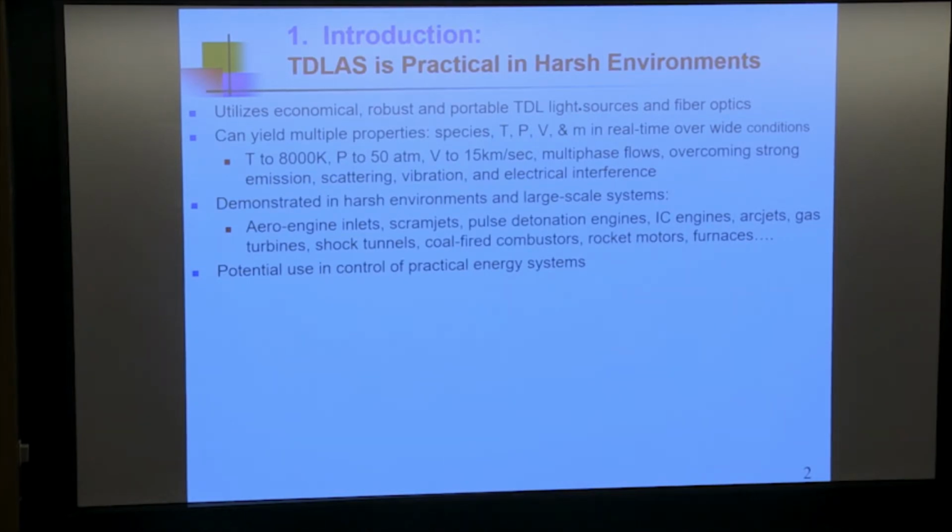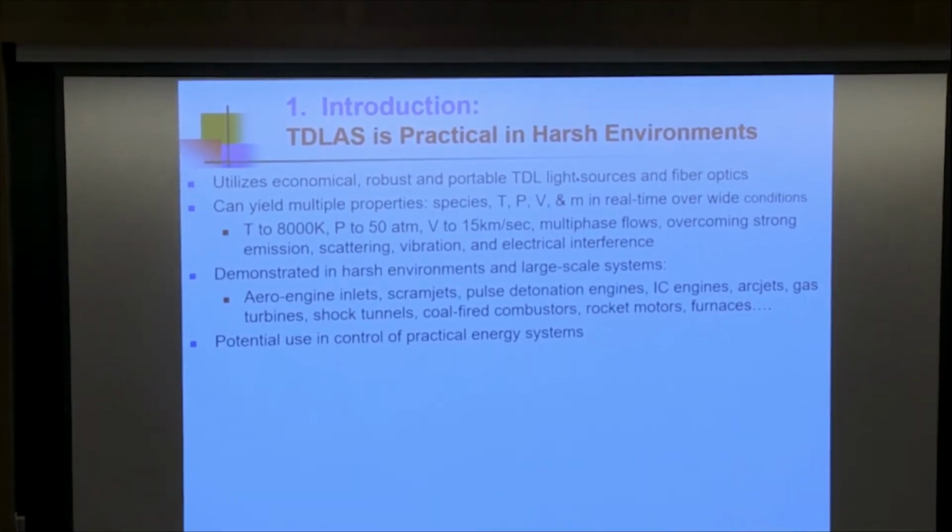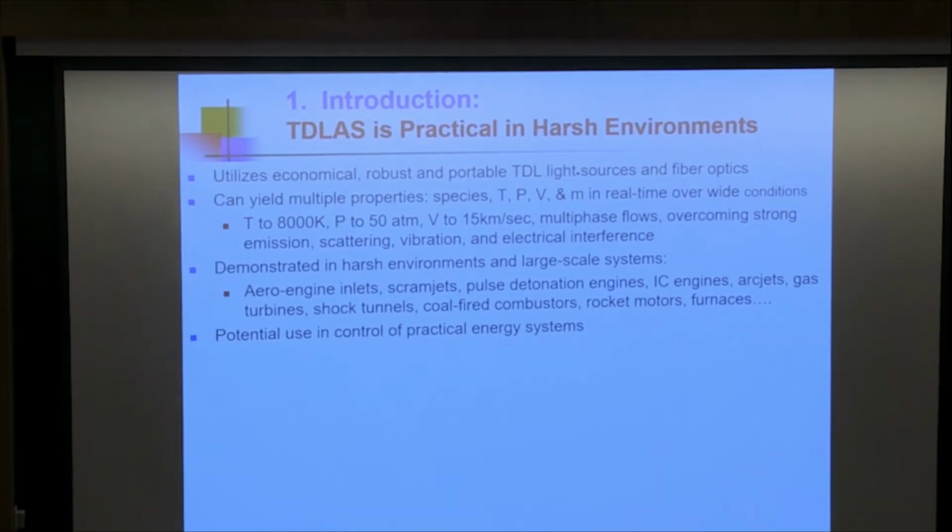And the main message is that this form of laser diagnostics is practical. You have to live with the line of sight aspect of it, but there are now so many wavelengths available with lasers, and absorption is so well understood, that you can engineer devices to work in multiple environments. And of course, these laser systems can be fairly economical. And I've shown you already, I hope, that we can measure species, temperature, pressure, velocity, mass flux, and so on.